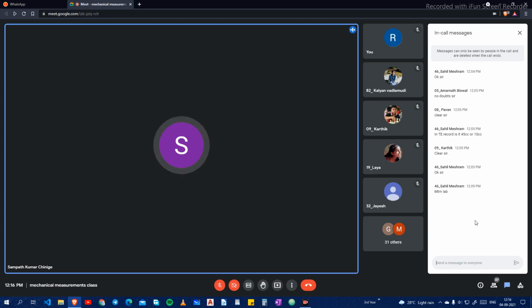What can be the reason? Which one will have more friction? I'm telling you, in one case, constant speed, there is combustion taking place. Combustion means the temperature of the materials is increasing. So now you can tell me. In the other case, there is no combustion, there is no temperature rise. Which case will have more frictional power?